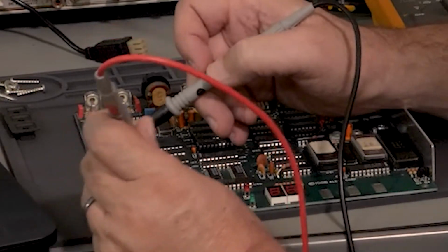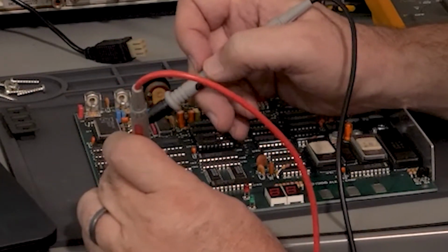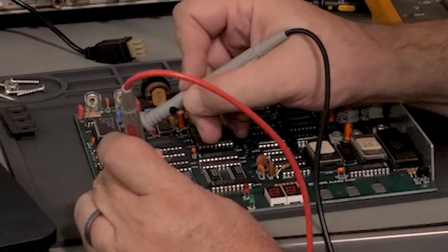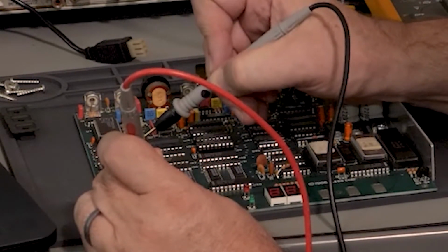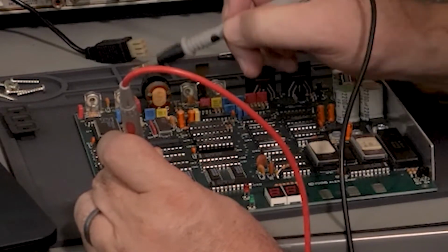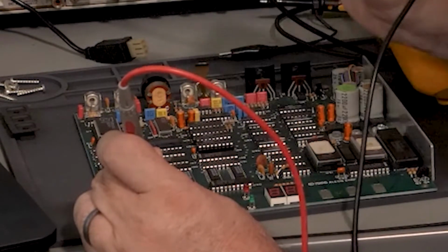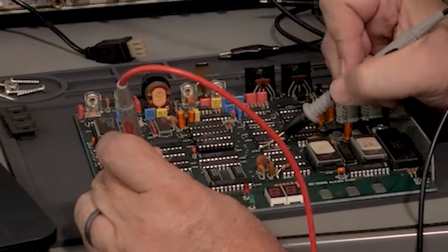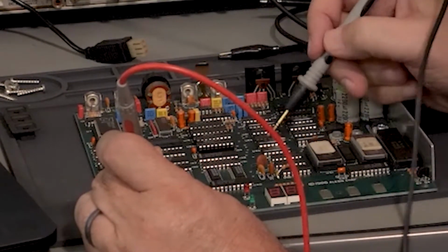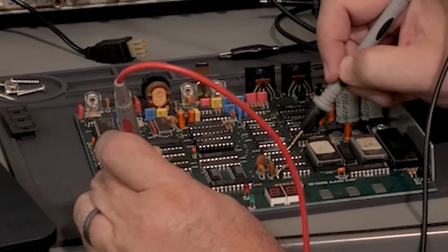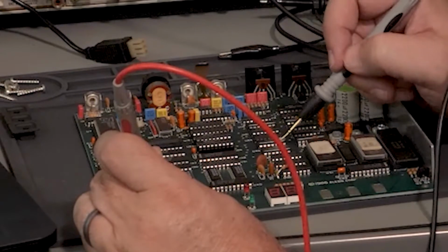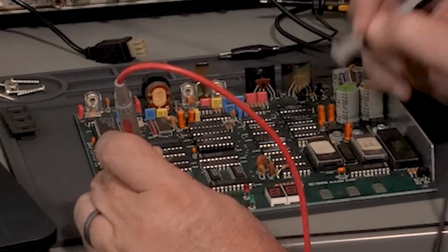To test that, I'm going to put it on ground right here. And all these chips are tied to ground. So if I take this part way over here and rake it, okay, it rakes on that ground, rakes on that ground. See, that's called raking. See that? I got 2 beeps on that chip because I got 2 pins tied to ground on that chip, and so on.